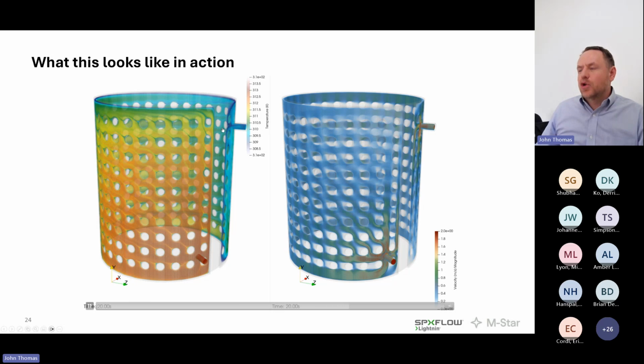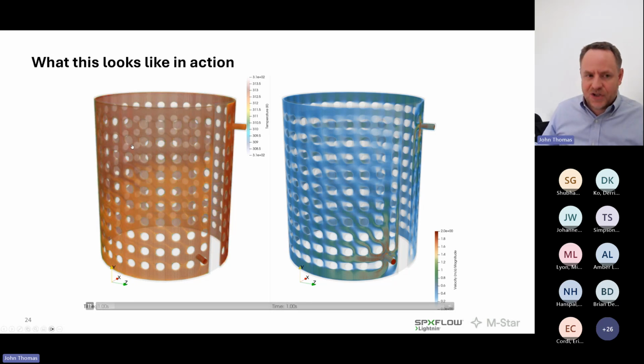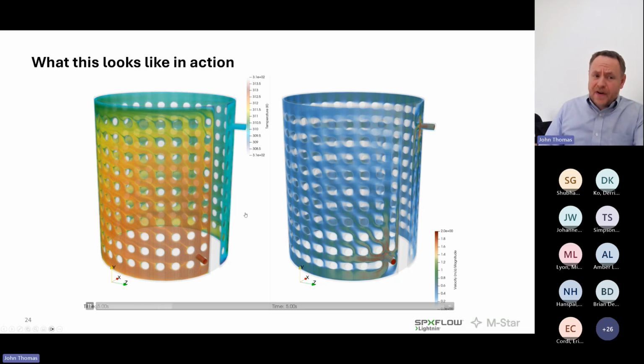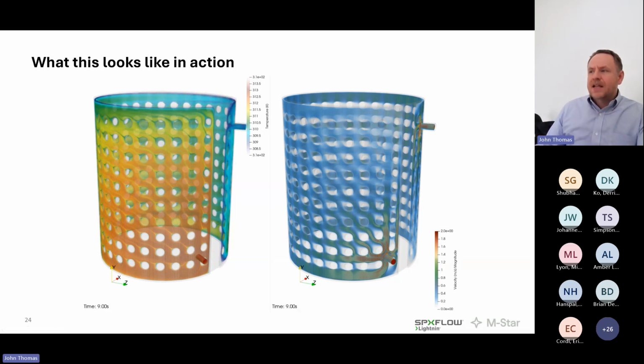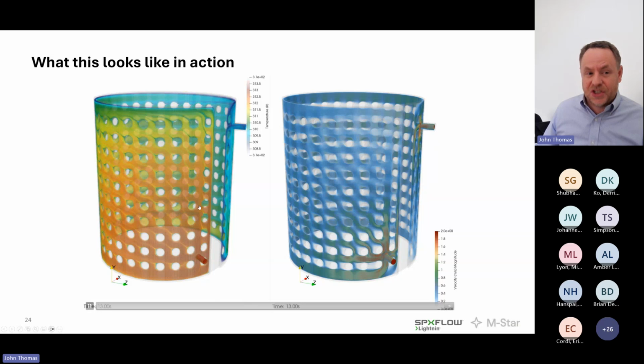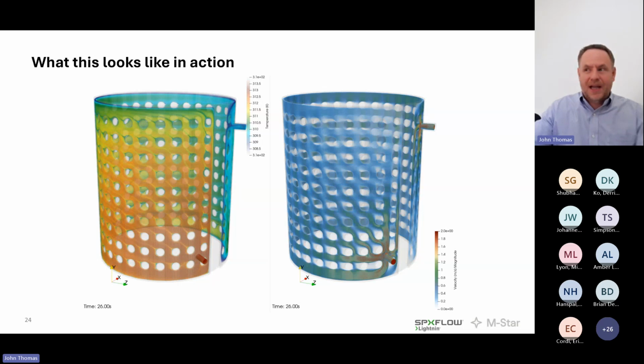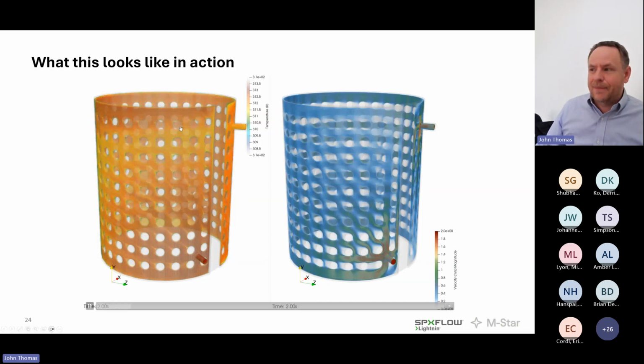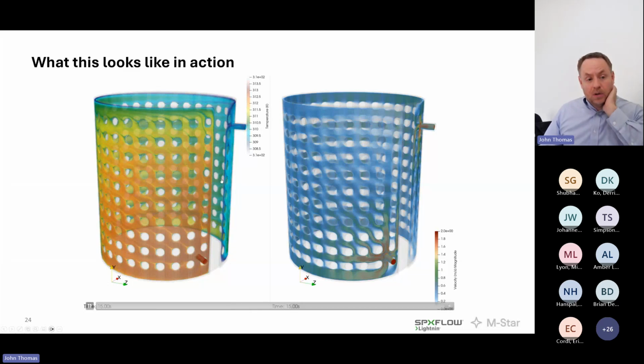So hot coming in, comparatively cool going out. And this is the temperature variation across that jacket. This temperature variation is necessarily going to lead to heat flux variations across the system due to the smaller driving potential. So again, if the fluid is well stirred, as it were, and effectively homogeneous temperature-wise with respect to this heating time, then the driving potential between the jacket and the process side will decrease in proportion to the local temperature in the jacket fluid.